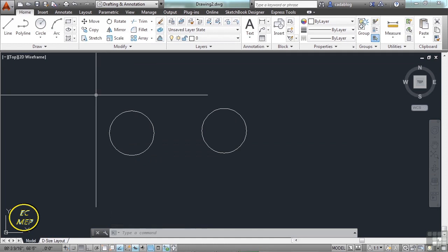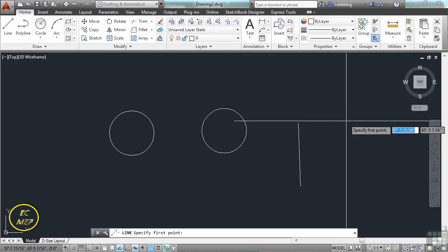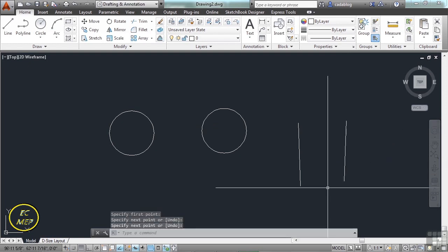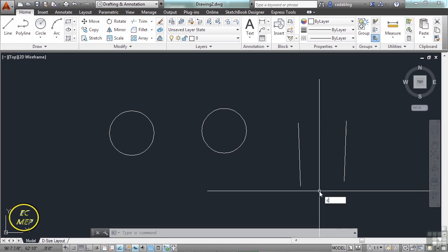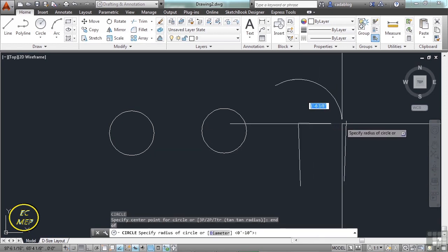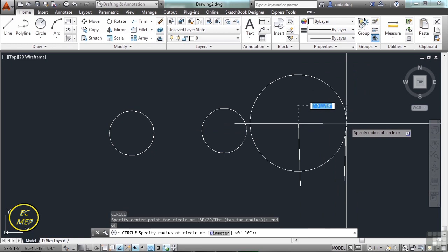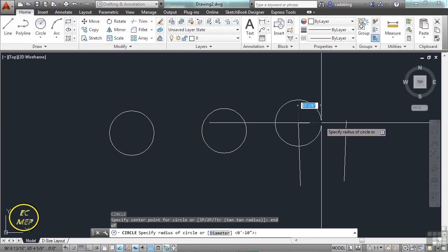That's important to know, because sometimes you have the diameter, and sometimes you have the radius. So, well, if I have one, I know what the other is. That's true, number-wise, but oftentimes when you're drawing in AutoCAD, for example, if I have this line and this line, and I need to draw a circle, what do I have? Do I have a radius or do I have a diameter? Well, that depends. If I start circle and I draw from this endpoint, and I want to draw to this endpoint, I have a radius, not a diameter. That's true. But if I want the circle to come to the middle of these two lines, I will need the diameter. I'll show you the difference.